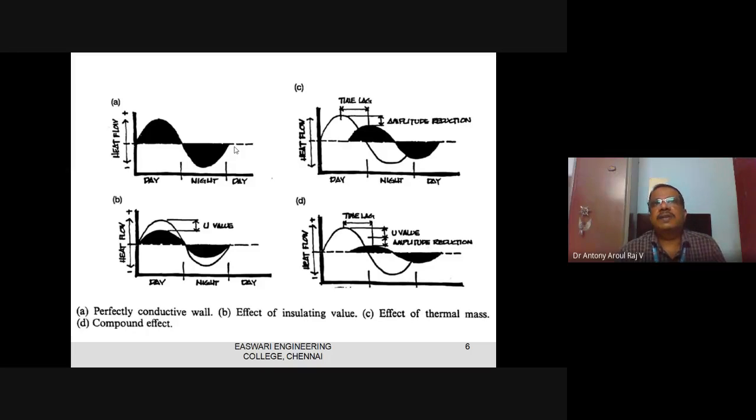But if you have tinted glass, or glass with insulation, double pane and other things, then you will have the insulation as well as the shift. This is a very important concept you should understand. For glass, the entry will be immediate. Similarly, outdoor air will be immediate, because at that point of time you take the outdoor temperature immediately. Outdoor air and infiltrated air enter immediately.